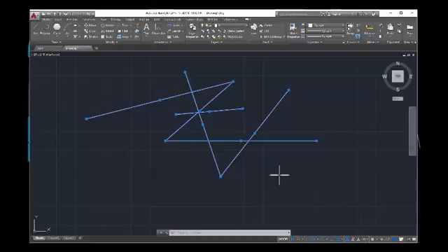If I hold down the Shift key and as I'm holding it, I move my cursor over one of the lines. Do you see that little minus sign that pops up? Might be easier to come over here. Minus sign. That little minus sign indicates that it will unselect the object if you click on it. And notice it only shows up at the center of your crosshair. So let's click that line. Oh, the blue went away and it is now unselected.